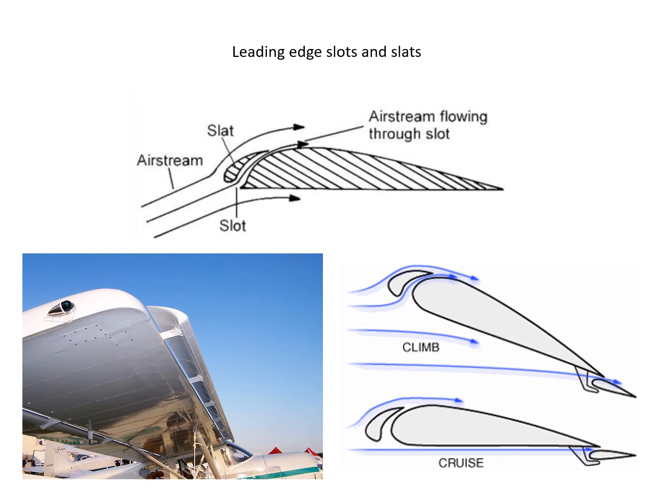So this slat would run the entire length of the wing, and it's wider at the mouth than it is at the back, so it's wider where the slot is labeled, and that acts as a funnel. So air enters that, and then it starts to narrow, and that speeds up the flow, and then that is directed down onto the boundary layer. And these allow planes to fly more slowly without stalling. So for a given angle of attack, it reduces the airspeed that they have to be at before a stall sets in.